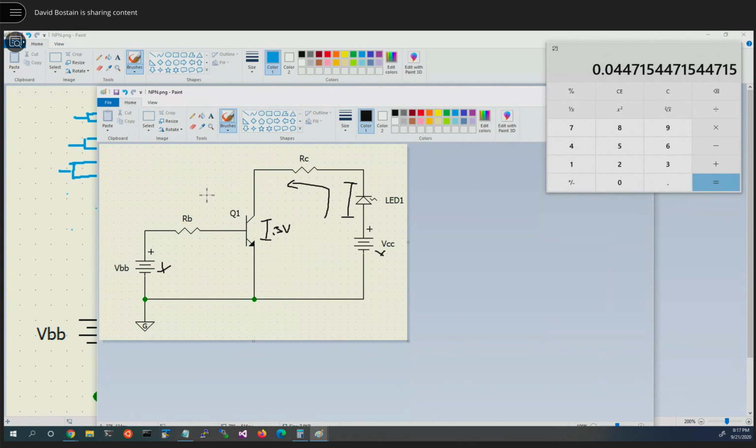I might give you a different value for beta. Maybe I'll say beta is 120. And you would still do all the solution, and the ultimate solution is tell me what resistor I need to go out and buy. And then you've made sure that it's safe, it won't burn up, it won't overheat, that it's got reasonable tolerances. Anybody have any questions about this?